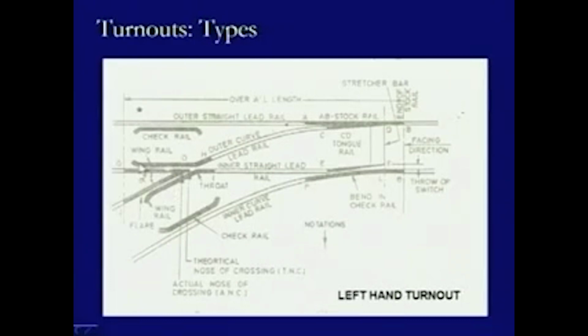Just opposite to this wing rail, there is another type of rail being provided on the other side of the rail section, on the inside of that rail section, which is parallel to that one and is flared on the two ends. So, this is another type of rail, this is one and this is one being provided on this side, and this is known as the jack rail. So, this is another component: the wing rails and the jack rails being provided on the crossing of the turnout.